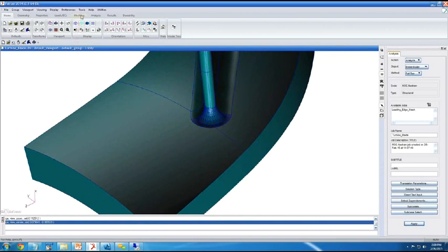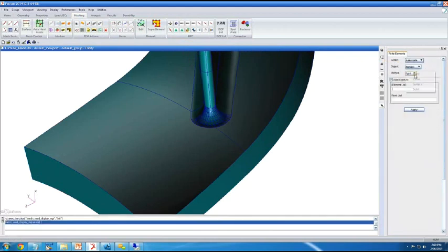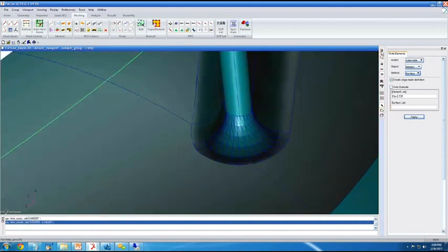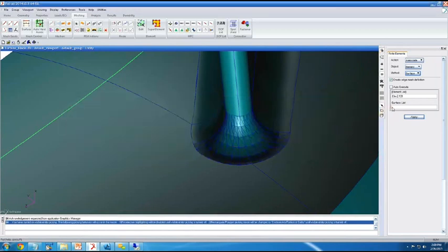We're going to go to Meshing. Going to go to Create, associate element with surface. Go ahead and select all of our elements. We're going to turn on visible entities only, to make selecting those solid faces easier. Click apply.